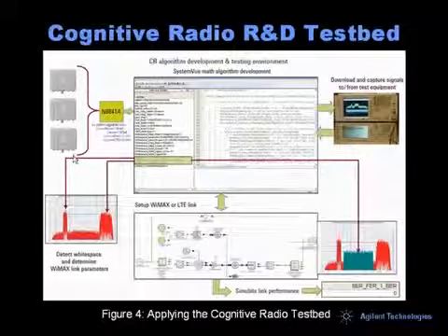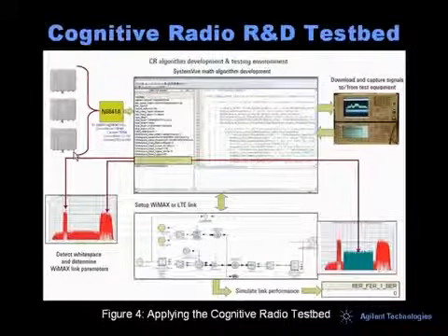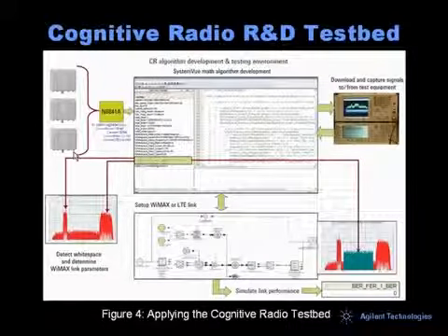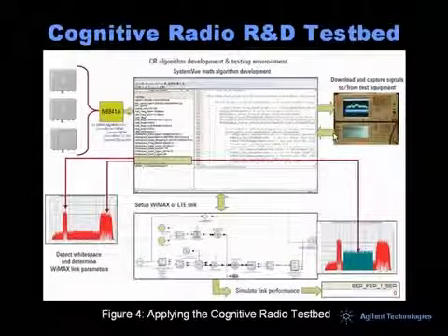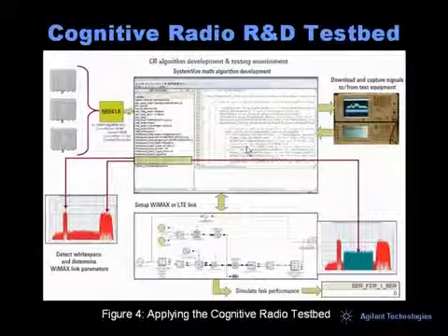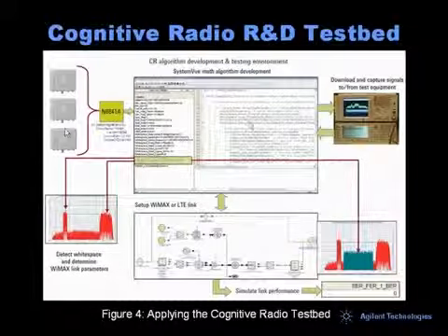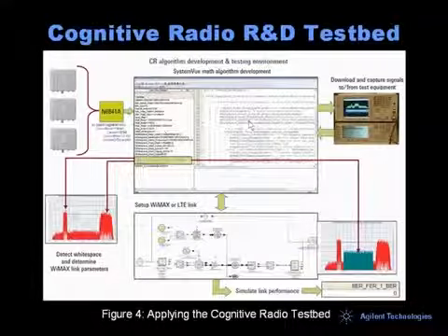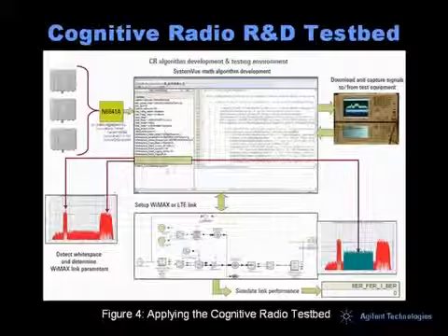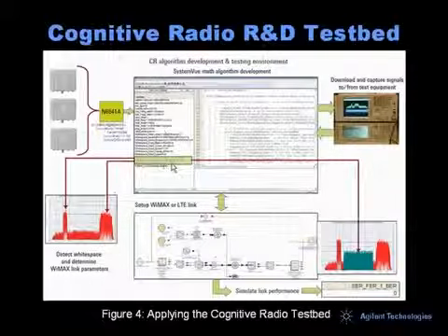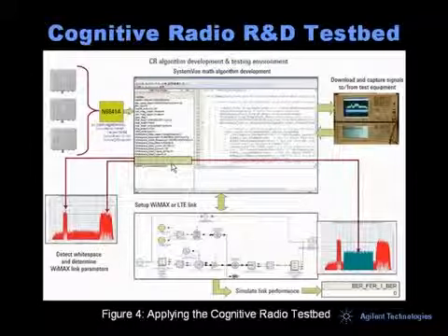The flow involves capturing a cognitive radio spectral environment from a remote field location. The sensor is located in western Washington State, while the simulation and test equipment are located in an office environment in eastern Washington State. SystemVue's math algorithm processes the captured cognitive radio spectral environment to determine potential white space. The potential white space frequencies are evaluated against a policy to determine valid white space frequencies and available bandwidth to support an OFDMA mobile WiMAX link.